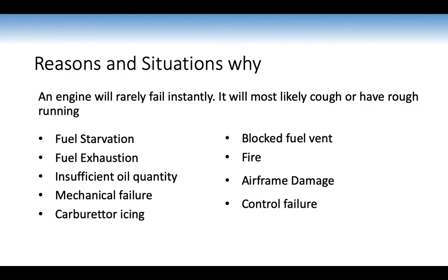Insufficient oil quantity will be an oil leak. Mechanical failure in terms of the engine and its components. There could be carburetor icing, which can lead to that fuel starvation. Blocked fuel vent. There could be engine fire, airframe damage from a bird strike, or a control failure as well. A lot of these issues can be prevented by having a good, thorough pre-flight. So we've got that threat of poor time management in the system. There will be not doing a good, thorough pre-flight, and the undesired aircraft state will be engine failure. So make sure you have a good, proper pre-flight for all lessons.